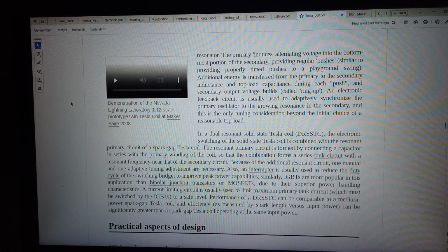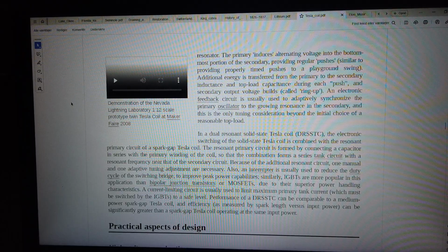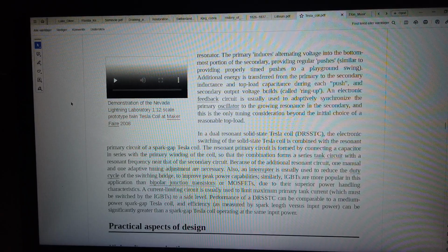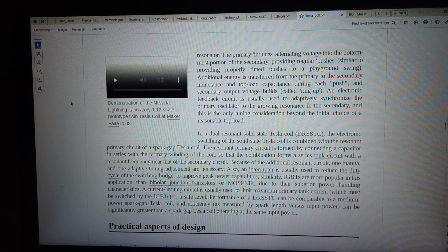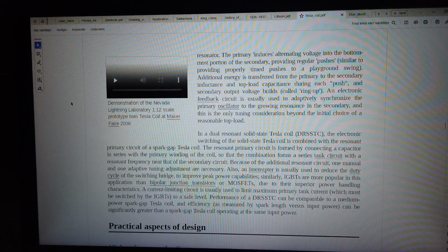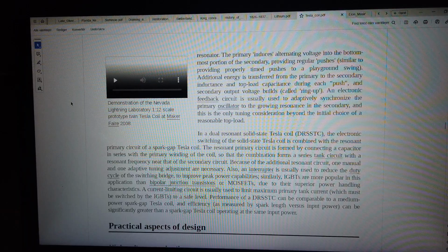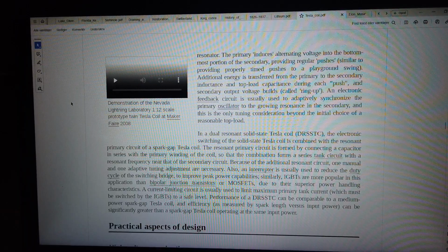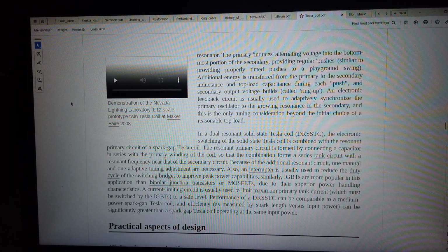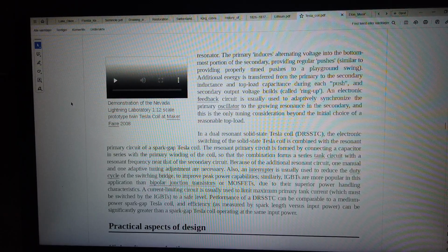High voltage production. A large Tesla coil of more modern design often operates at very high peak power levels, up to many megawatts, millions of watts, equivalent to thousands of horsepower. It is therefore adjusted and operated carefully, not only for efficiency and economy, but also for safety. If, due to improper tuning, the maximum voltage point occurs below the terminal, along the secondary coil, a discharge, spark, may break out and damage or destroy the coil wire, supports, or nearby objects.